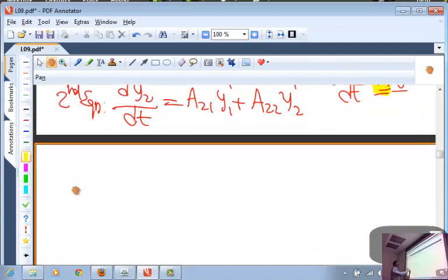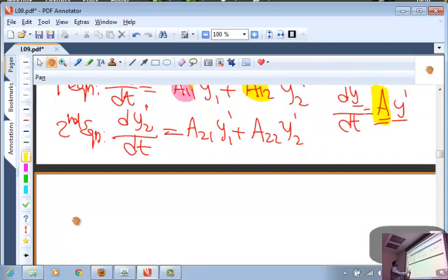So we have a linear system and we have related now how to get the stability of a nonlinear system for local perturbations. Okay? Linearize the process, get the eigenvalues, and everything that we have seen for linear dynamical systems, either being a node or a saddle point, all those concepts will carry through for this particular problem. So how do I find the equilibrium solution? Before I can calculate these coefficients A11, A12, A21, A22, I need to know where the steady state is in the state space. Okay? How do I do that?